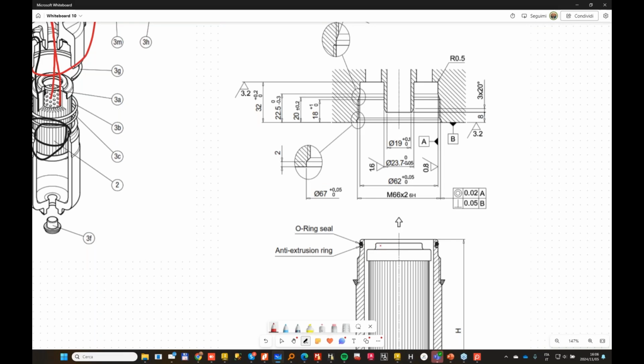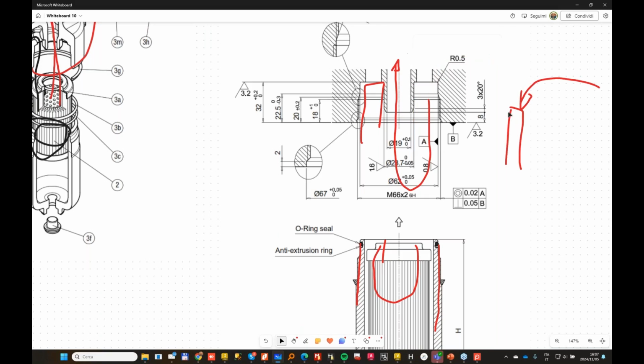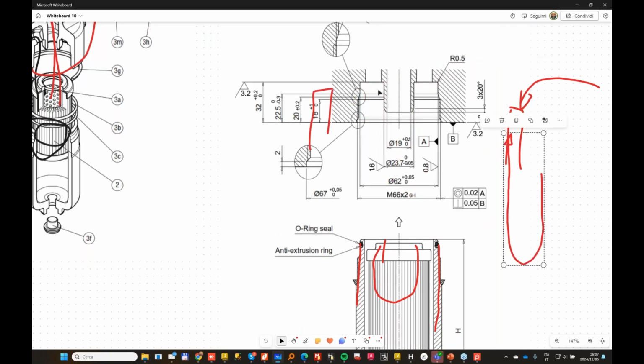The cartridge is made of two elements, the filter element and the bottle, the external. So the filter element will enter here. The oil will come inside from the radial diameters, and then it will enter inside. What is particular of this application is that practically the geometry in the manifold must have this protrusion inside, because it must keep separation between the inlet and the outlet of the filter.